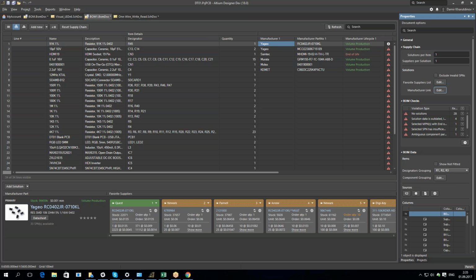So make sure we have a way to turn off the cloud search when we do the BOM. This has been a source of significant performance hits. That was specifically what we were addressing. With the new BOM engine, we were able to refactor and redo the way we retrieve data. From now on, it's done in an asynchronous way, in multiple threads, and there should not be significant impact. If you still see that, please report it in a forum.